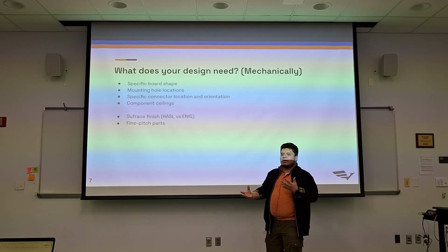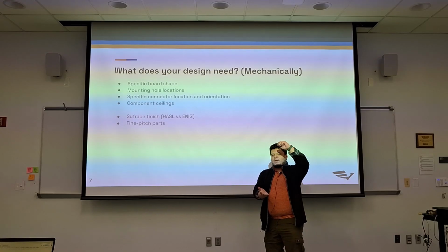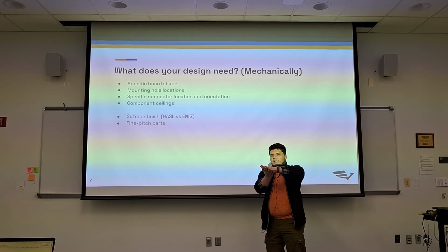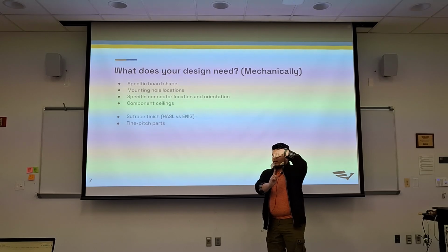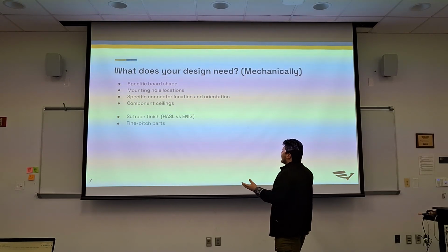What is the orientation of all the connectors? Where's my pin 1 going, right? Because maybe I'm stacking on top of another connector. And if it's a stacking connector, you want to make sure your pin 1 aligns with the other pin 1, right? You've got to think about the entire system.